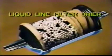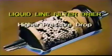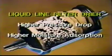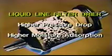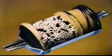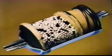If they are liquid line filter dryers, they can have a higher internal pressure drop, but their adsorbing ability must be high to ensure that no contaminants dissolved in the refrigerant reach the expansion valve. Because liquid line dryers are designed for higher adsorbing strength, installation of a liquid line dryer is a must for making sure the system remains clean of moisture and debris.